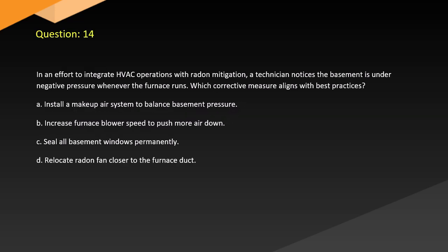Question 14. In an effort to integrate HVAC operations with radon mitigation, a technician notices the basement is under negative pressure whenever the furnace runs. Which corrective measure aligns with best practices? A. Install a make-up air system to balance basement pressure. B. Increase furnace blower speed to push more air down. C. Seal all basement windows permanently. D. Relocate radon fan closer to the furnace duct.